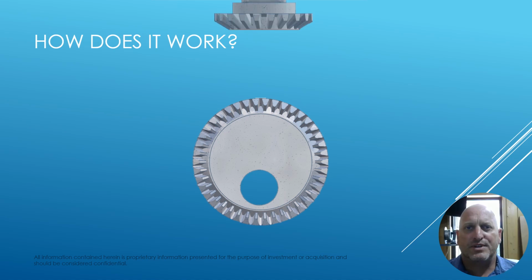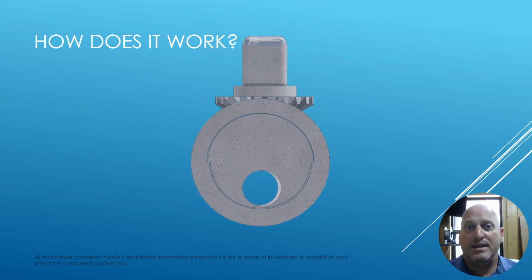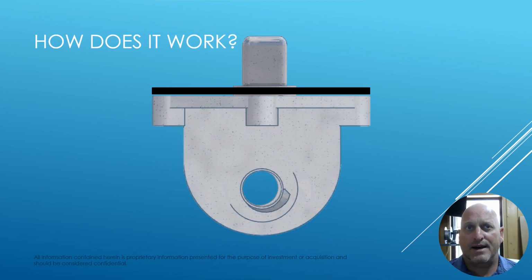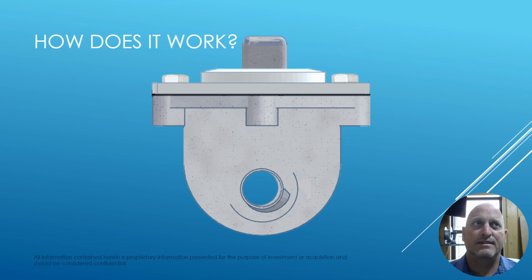It's pretty simple. So you have two bevel gears that are driven by a beveled pinion gear. And when you put those into the body of the valve and have a cover with valve stem on top of it, 6 bolts will hold this entire mechanism together. So that means that not only is it very simple, we actually have very few parts to manufacture, but the way that it works is that we can sell the valve, and if you have